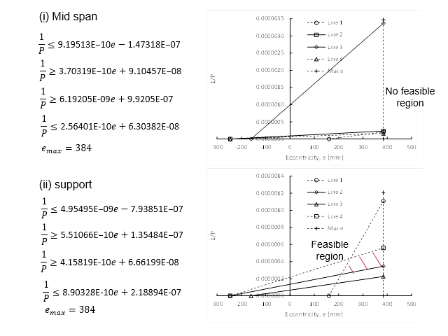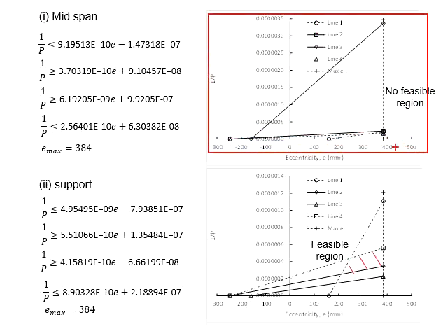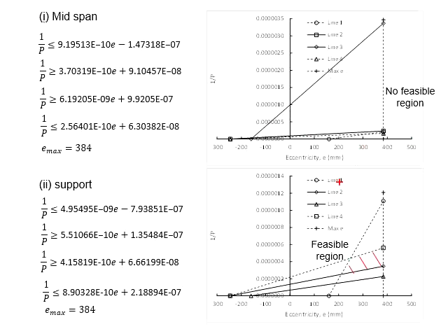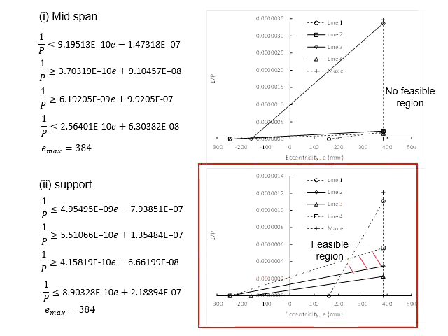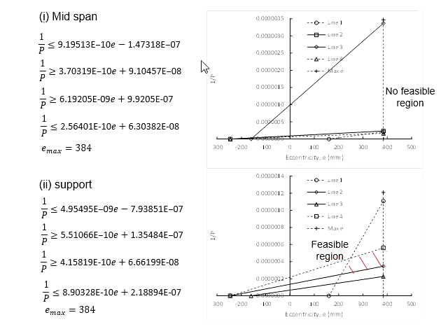In this case, you will have to redesign these sections until you have worked out a feasible regions within the midspan. As for the support here, the Magnel diagram looks nice. The hidden line means lesser, solid line means greater, and the maximum eccentricity means lesser here. There will be a regions of feasible region. That means for the support here, you can propose appropriate P and E within the regions here.